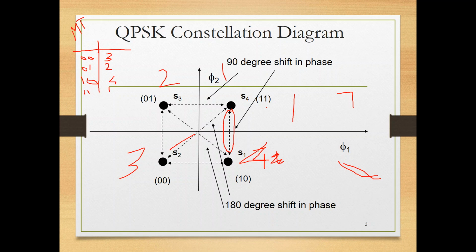We like to have smooth transition, not sudden, so that the amplitude or the signal stays continuous, not discontinuous. So basically, this is what motivates the study of offset QPSK. This is why we are studying offset QPSK, and this is the key difference between QPSK and offset QPSK. Offset QPSK tries to avoid these transitions.